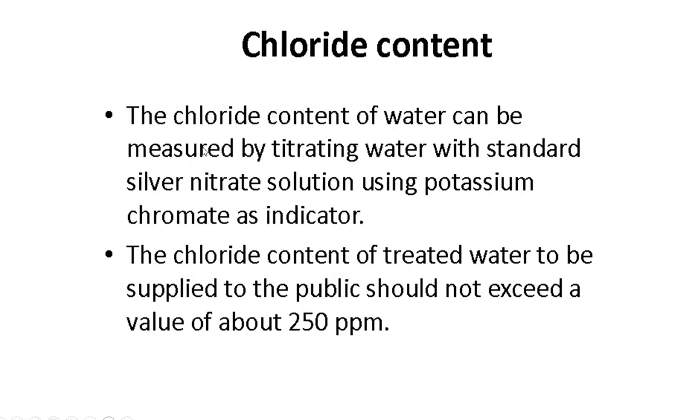The chloride content of water can be measured by titrating water with standard silver nitrate solution using potassium chromate as indicator. The chloride content of treated water to be supplied to the public should not exceed a value of about 250 ppm, parts per million.